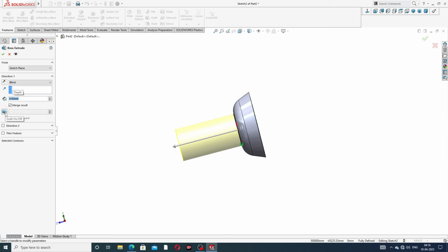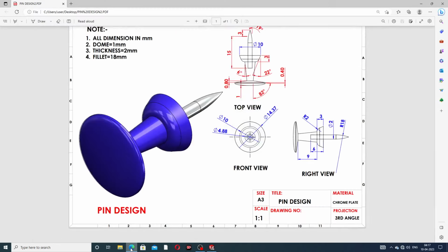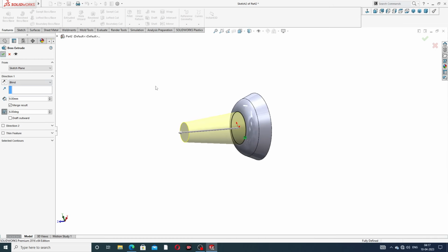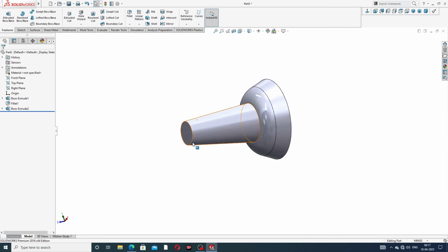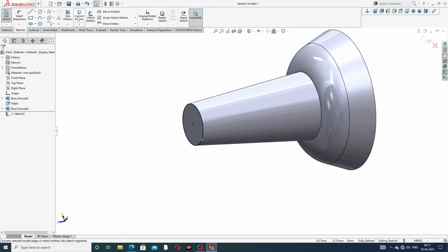And also this draft angle, this draft uses a 6 degree angle. Okay, this is perfect. This uses a 6 degree angle, and this length is 9 millimeter, and correct. Okay, this is perfect. Next, also on this sketch, use Convert Entities.